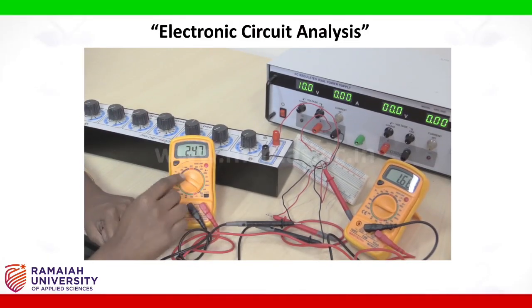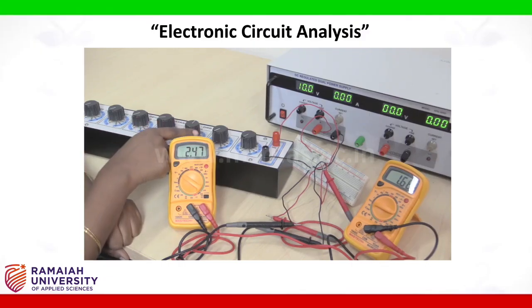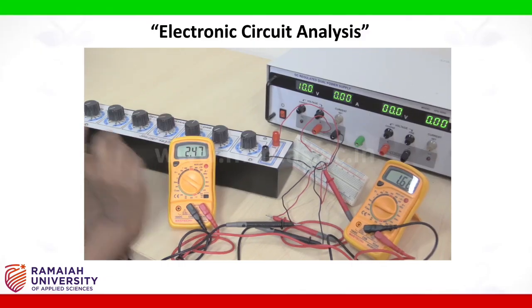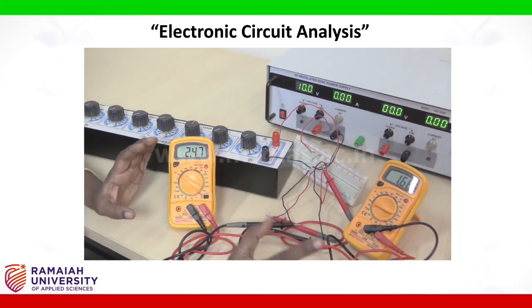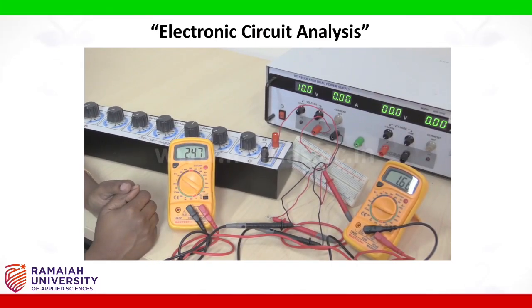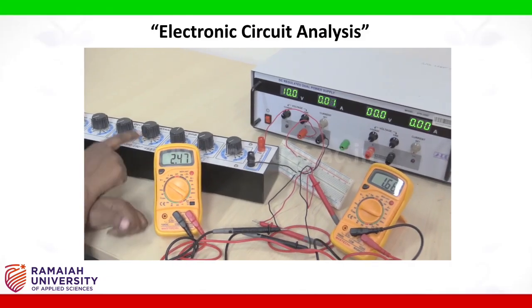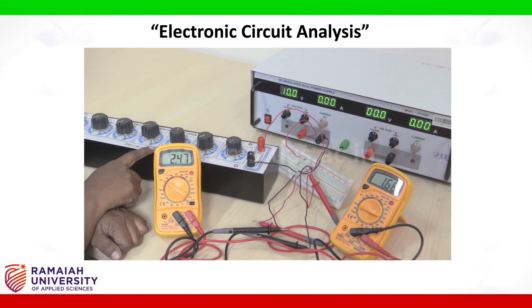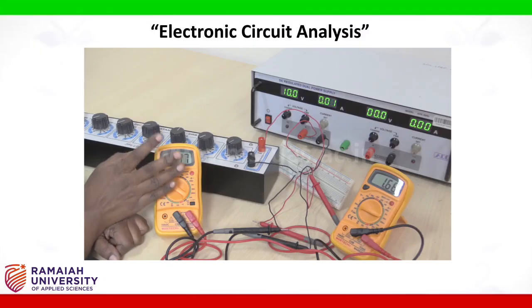Repeat this way of tabulating till the load resistance in the DRB becomes 2.5 kilo ohms. Note all the readings in the table. You will find that maximum power will transfer to the load when the load resistance is 1.5 kilo ohms. This verifies maximum power transfer theorem.